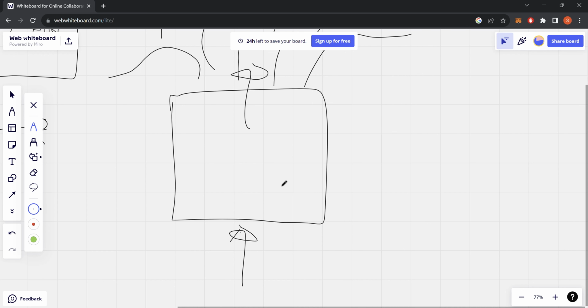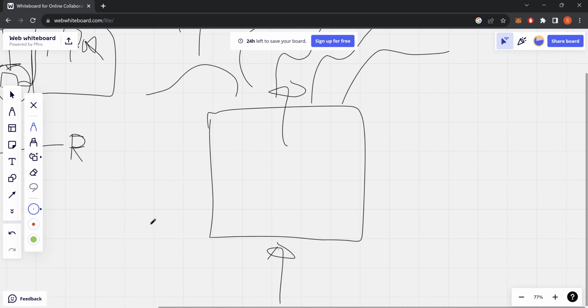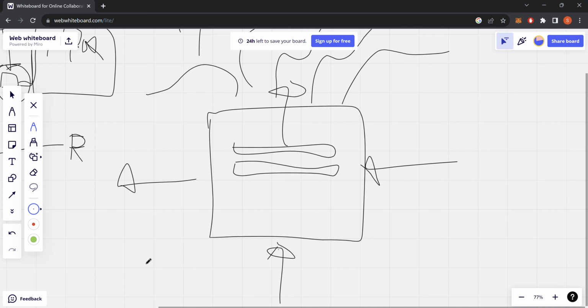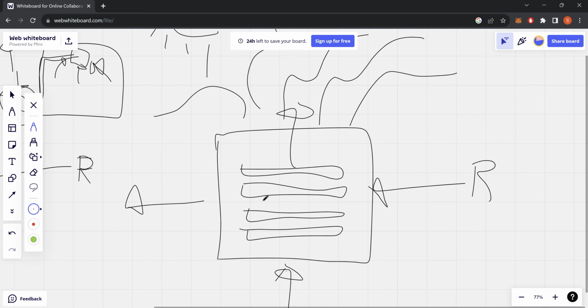So there's airflow coming through this side, and then there are the evaporator coils, which are designed to do effectively the same thing as the condenser coils, but in the opposite way. So the refrigerant lines are going this way, right? So you've got the same thing. You've got a whole bunch of aluminum fins, a whole bunch of tubes of this fluid in contact with these aluminum fins, right? So the refrigerant, as it moves through these, is going to pick up energy from the air temperature, from the air from the inside of the house, and it's going to bring that energy out of the house.